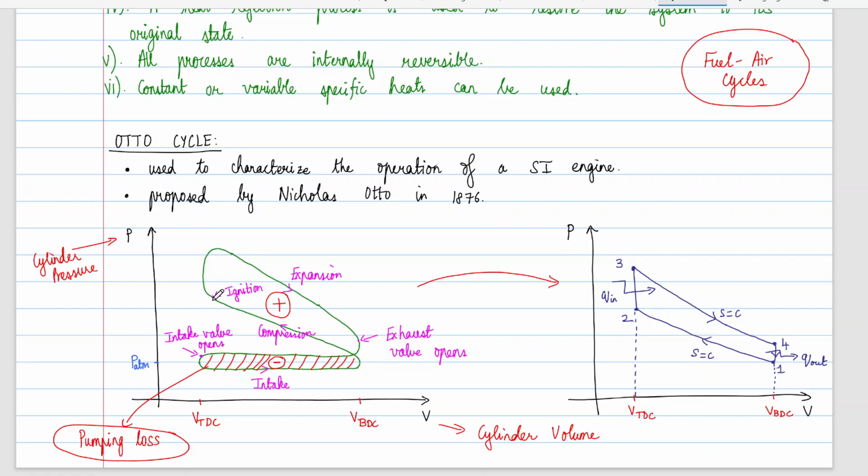Sorry, yeah, ignition happens, that is the spark plug ignites the fuel air mixture, and because of it combustion happens. As the combustion happens, the fuel air mixture starts expanding. With this expansion, power is put into the system, that is combustion energy essentially pushes down the piston, converting that chemical energy to mechanical energy. And while this is happening, we'll reach the bottom center.